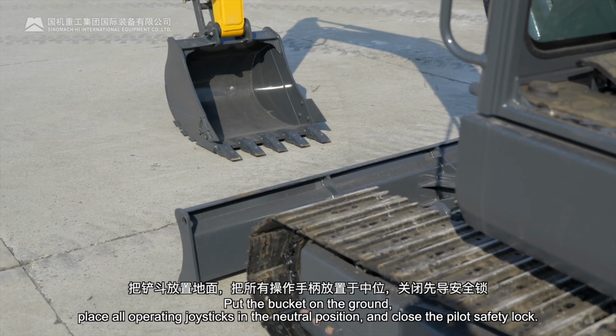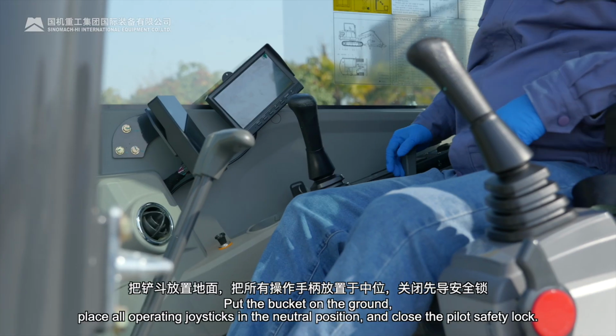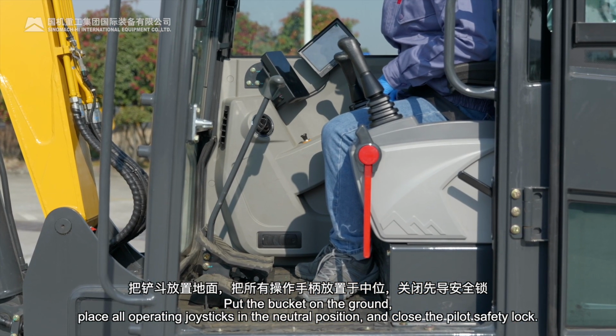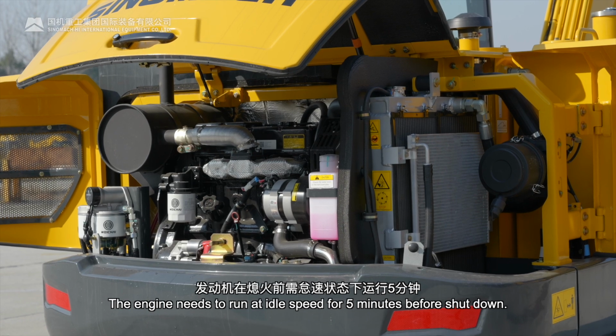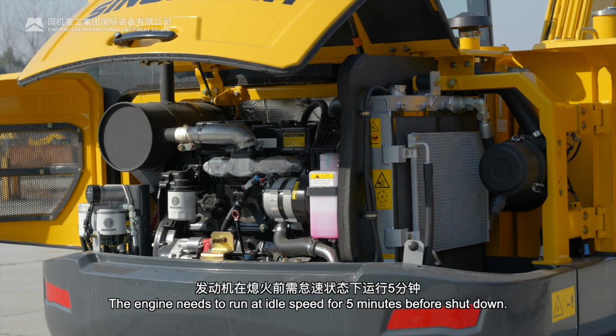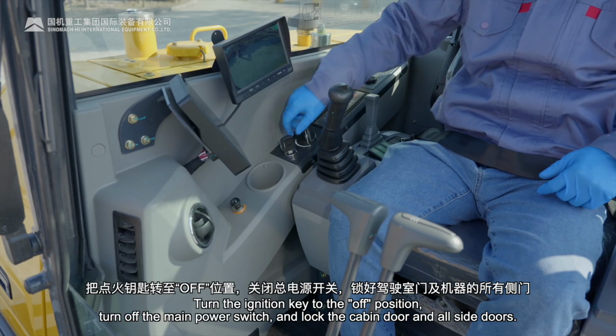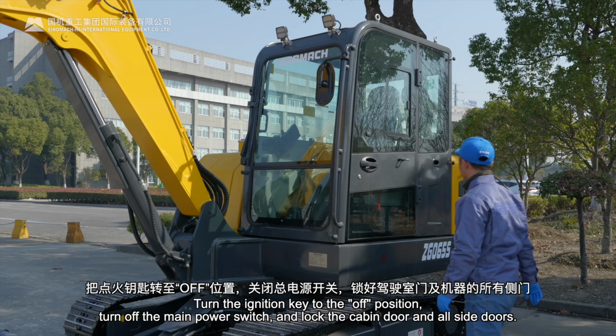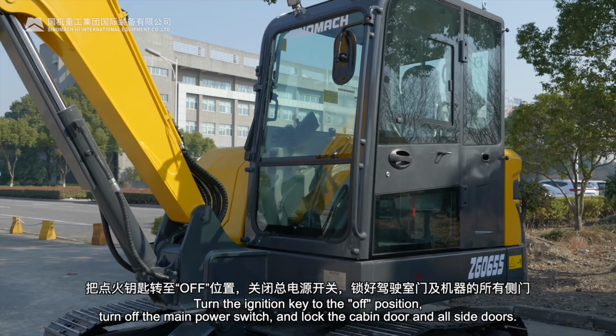Put the bucket on the ground, place all operating joysticks in the neutral position, and close the pilot safety lock. The engine needs to run at idle speed for 5 minutes before shutdown. Turn the ignition key to the off position. Turn off the main power switch and lock the cabin door and all side doors.